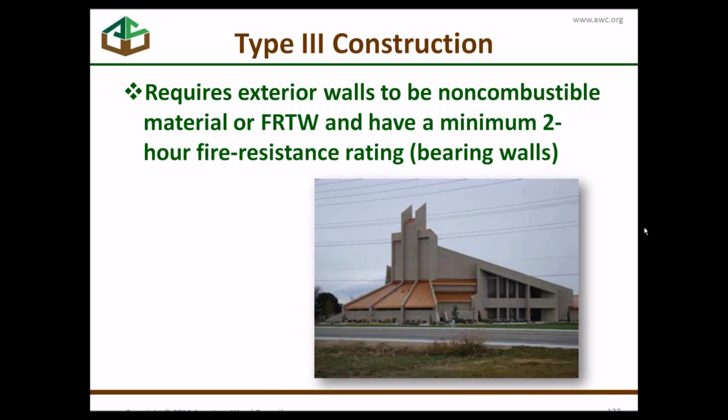These were describing, originally in the legacy codes, buildings in urban areas with rather tight spacing in perhaps a fire district. Exterior walls of masonry to prevent conflagration or to give some protection, at least from a fire safety standpoint. And then the interior would be heavy timber or wood frame construction.